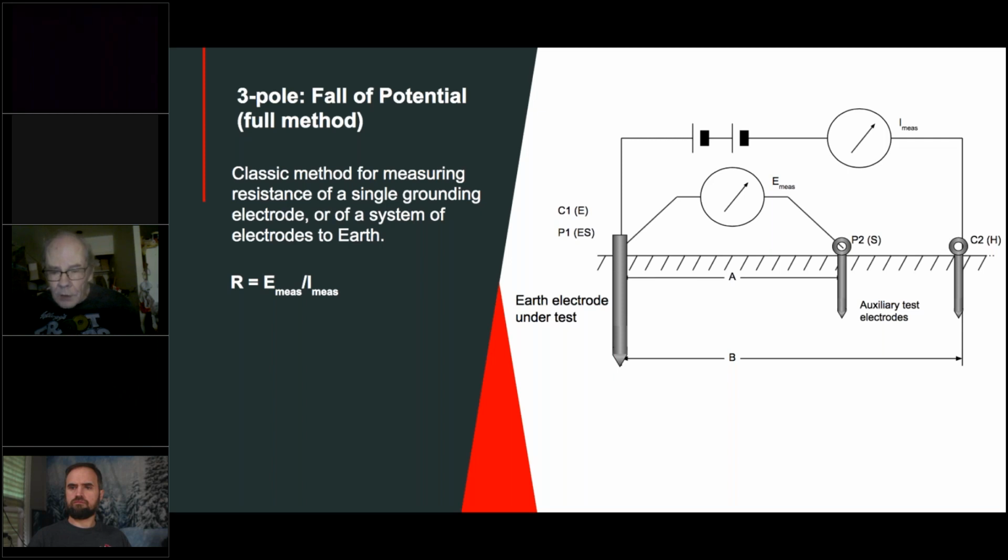When you energize the tester, that puts a test current in the ground from the current probe to the ground electrode you're measuring, and the tester uses that current to make its measurement. This is an alternating square wave. You do not put a DC current into the ground. A DC current would be far too subject to interference from other problems and things going on in the soil.